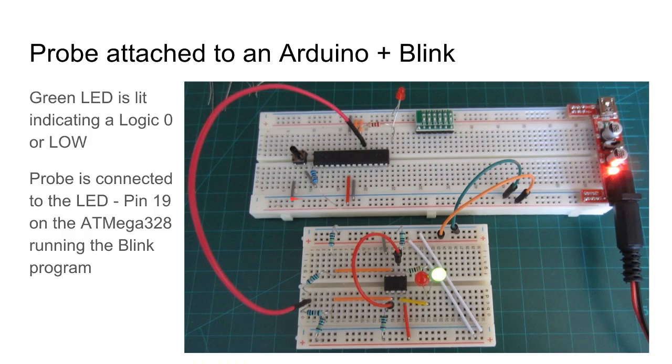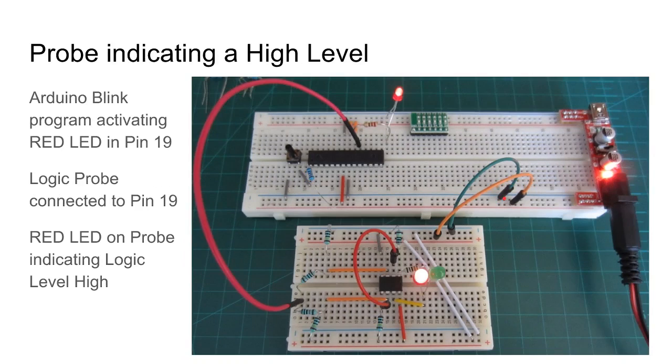So if this were a TTL or a CMOS type circuit, it would work just as well, because the resistor dividers will have a threshold within fractions of the circuit voltage that you're using. So in the next photo, the LED of the Arduino is lit up, which means that pin is sending out a high signal.